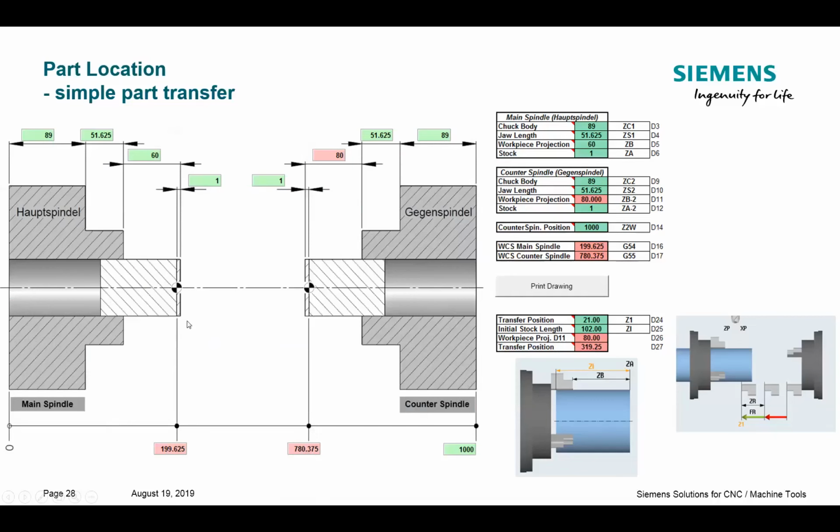So generally speaking, when I go to pull back, if my tool's not touching or overcutting, I messed up this number. And I either messed it up because I didn't accommodate for stock properly, or one of these values didn't work out. But this is that magic number. This is where I'm driving the counter spindle to during the part transfer. Hence why we call it transfer position.